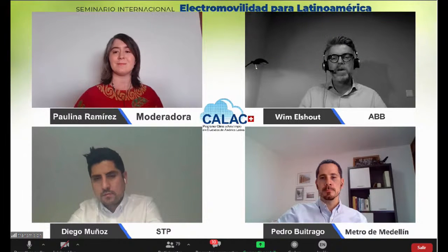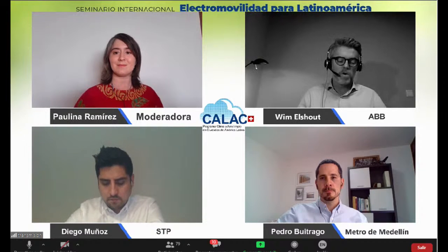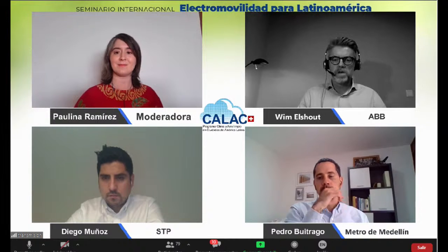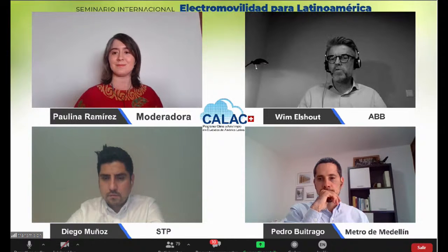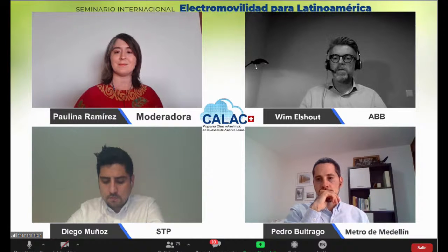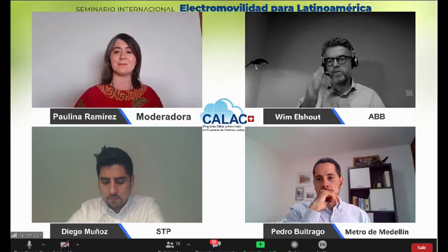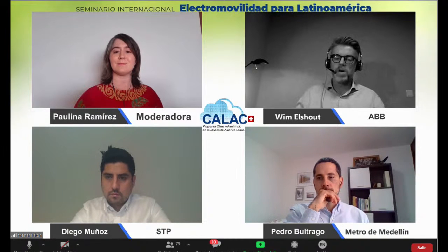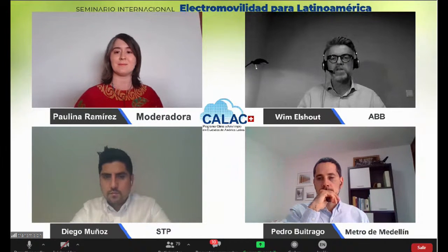It's happening today. And in fact, today I had a meeting with a customer in Santiago who is operating a number of electric buses and who's using our infrastructure to charge the buses. The first thing that they've done to manage the energy is to make use of sequential charging, so that you can hook up 3 buses to one power cabinet, and the charging cabinet will charge one bus after the other bus. So you need 2 hours plus 2 hours plus 2 hours to charge the bus. That's the first thing that they've done to manage the energy.